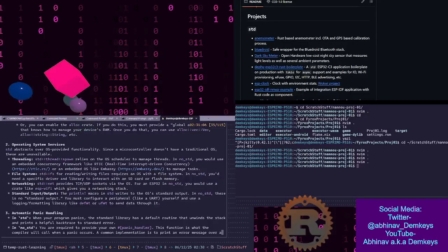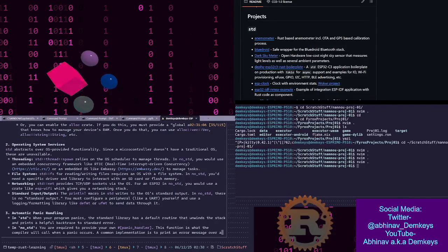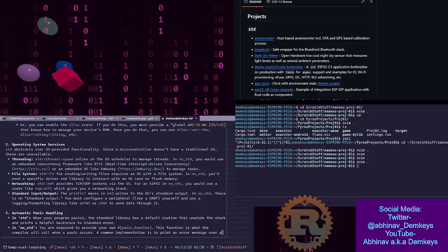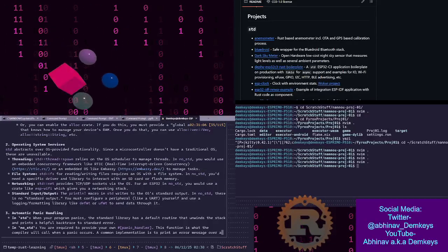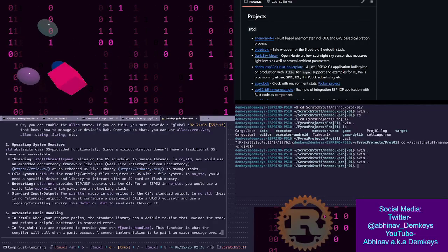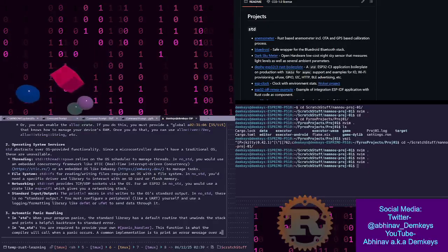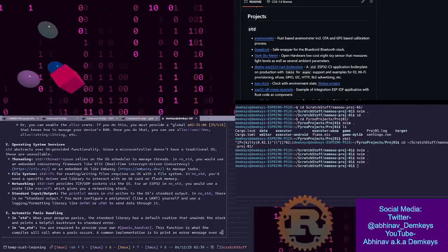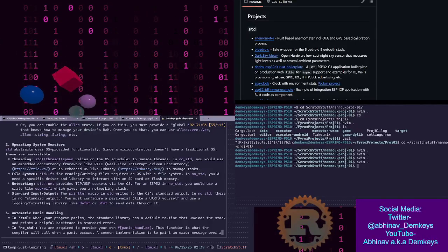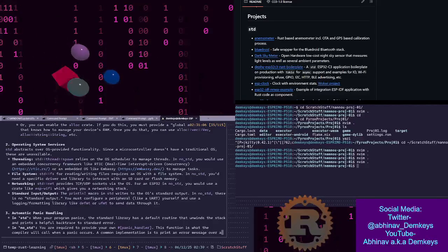So networking, to a certain extent, is available through other stacks, through other crates in this case. Standard input output, the print line macro. That makes sense, because it doesn't have anything to output to. In no STD, there's no standard output. You must configure a peripheral like UART yourself, and use a logging library to send data through it. I should keep in mind that this is an option.